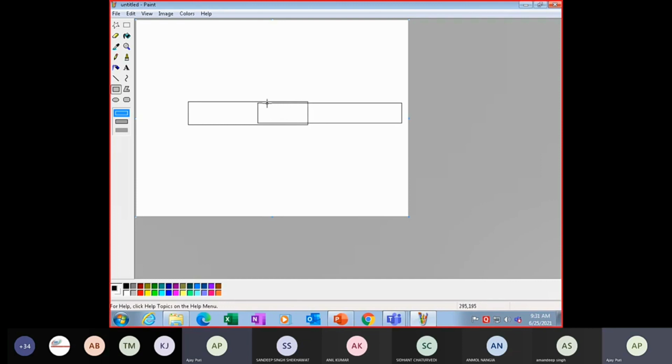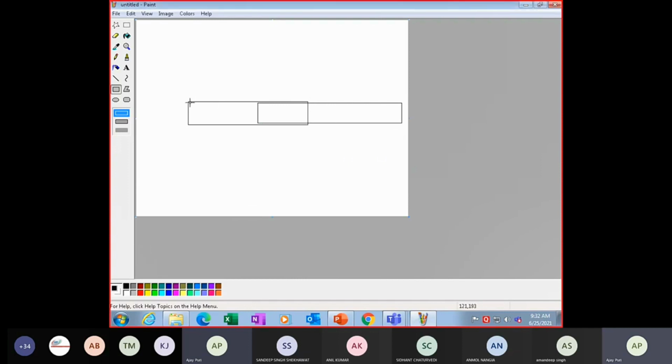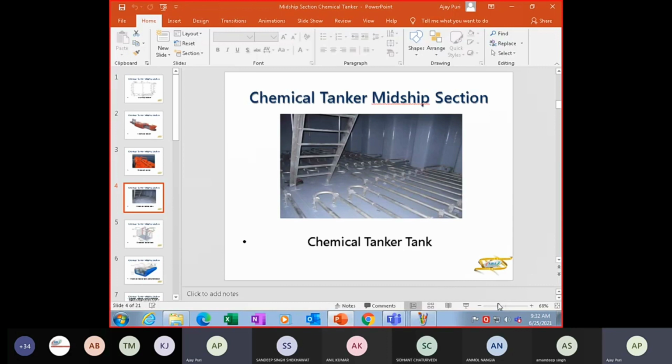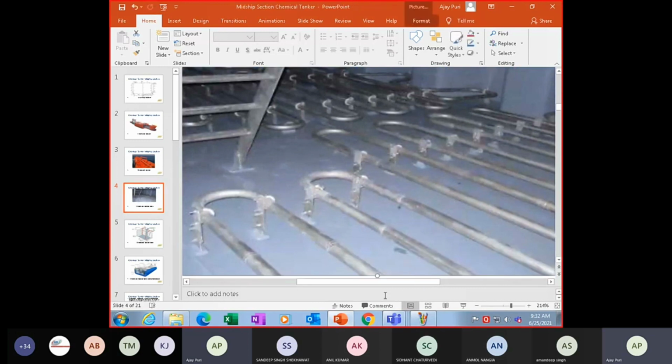So it is, you don't have a regular welding, but this is sleeve jointing so that it can take the pressure. That means if they expand this area, then the pipe is stuck inside, and then they weld here. So that is sleeve jointed, which is done for the pipelines to be seamless. Seamless means it looks like one pipeline. It will not look like any welding was done there. Here if you look, you can't see any welding. One minute, I'll enlarge it and show you. Look, this is sleeve jointed. Here you will not see any welding. This is inserted inside and sleeve jointed here.